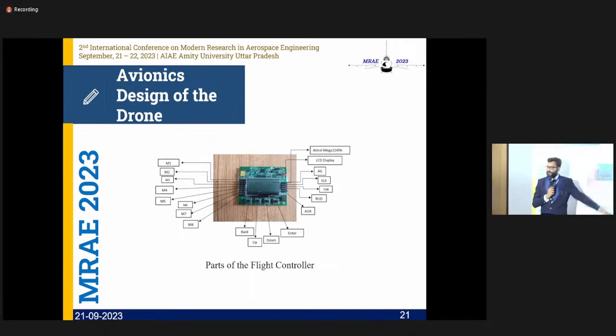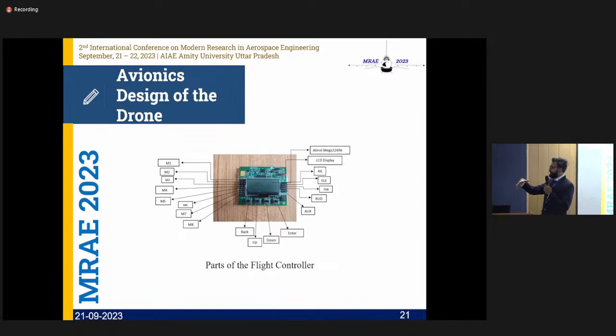Generally, we use the aux cable in our quadcopters when we want to drop something. Let us say you want to drop a ball or some payload. In that case, I can use the 5th channel, the auxiliary channel, through a servo motor and a small box door kind of mechanism. It's very simple, we will be able to make that. For that purpose, this KK2 is enough. If you go for competitions, national or international, this is enough. But if you want an application with sensors enabled, then you should go for APM or Pixhawk.